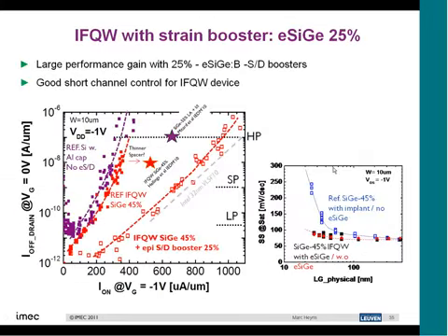So that's why these devices, this is an illustration of a silicon germanium device you made that way with strain boosters, actually perform extremely well. This is the red curve here. This is the typical I-off current. So this is the on current of the device.